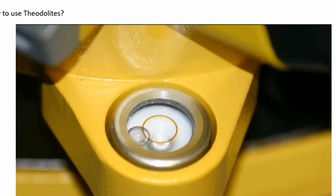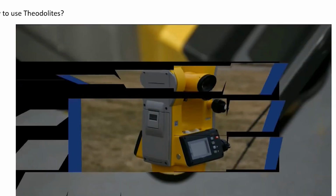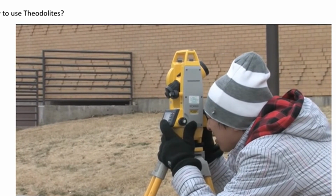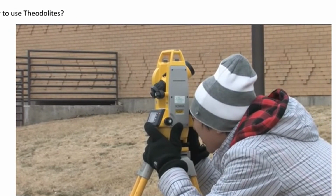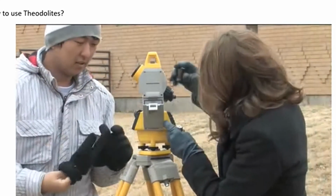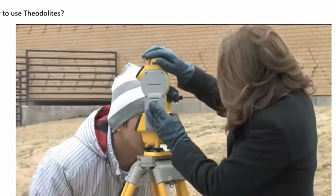Next, ensure the instrument is level by adjusting the 3 leveling screws on the tribrach at the base of the theodolite. Ensure that the bubble is at the center of the circle on the level. To verify that the vertical axis of the digital theodolite lines up perpendicularly to the center of the traverse cap, use the optical plummet located at the side of the instrument to look through and verify that the circular rings are on the center of the circular traverse cap. Next, open the battery door located on the side of the theodolite and insert the 2 C batteries located in the case, paying close attention to the positive and negative polarities.